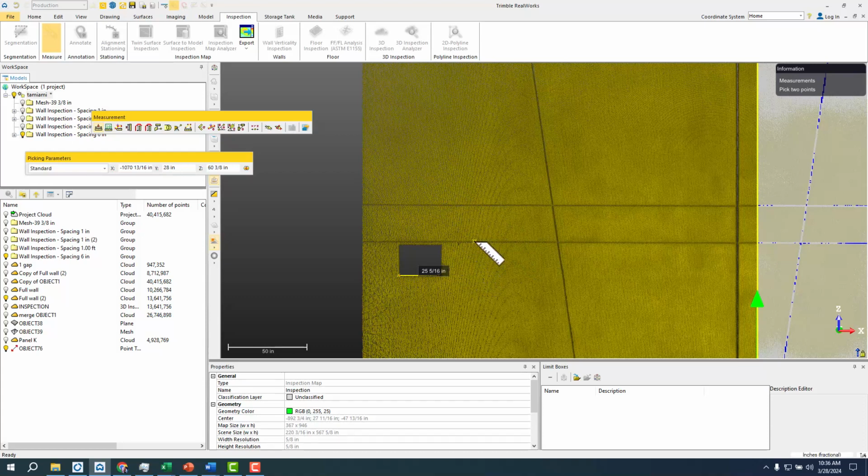I could run that same inspection in FieldLink, or do a little bit better analysis there with some DWG lines and specific points that can be exported in RealWorks here. So thanks. This is a lot to cover, but there's a lot to do. Talk to your structural engineer about what the specs are and your project manager, scan it, and then you can run through that analysis and actually make sure everyone's within that 1/2 inch or inch, whatever the spec is, to make sure it aligns well.